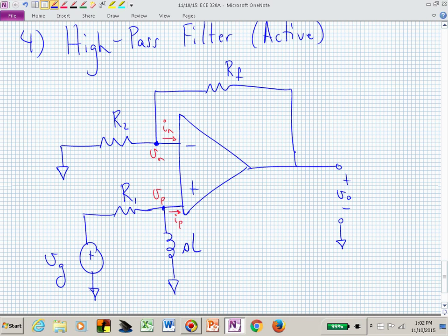And what do we need these op-amp circuits usually to be? How do we have them configured for them to play nicely? We need negative feedback. Does this have negative feedback? Yes, it does, because we are actually feeding back this output waveform into our inverting terminal. That's now giving us the negative feedback.